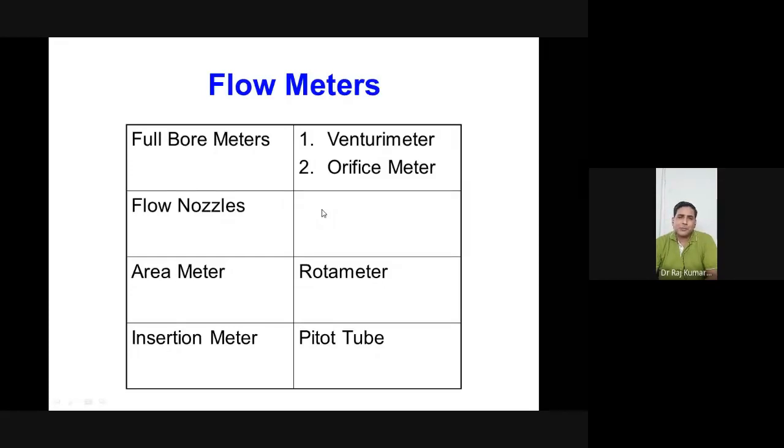So you are just putting a loss coefficient there, due to the sudden contraction and all this. You are applying Bernoulli, fine, but at the same time you are having a loss coefficient term. Therefore you get a discharge coefficient. The discharge coefficient in an orifice is not 1, it's 0.61. That is the loss only because of that sudden contraction.